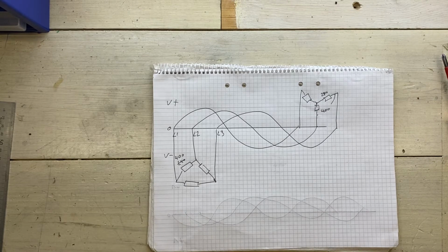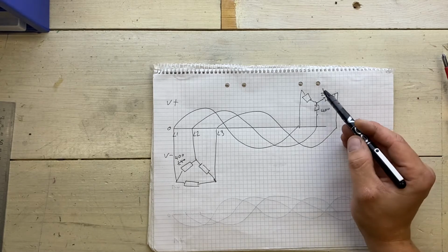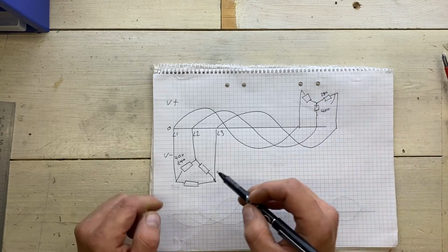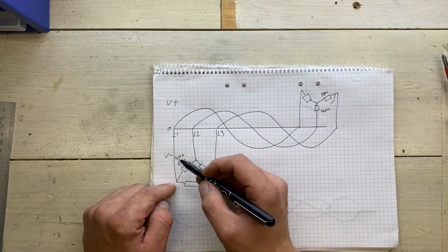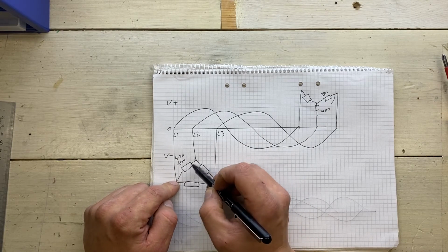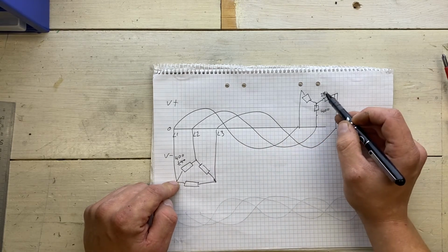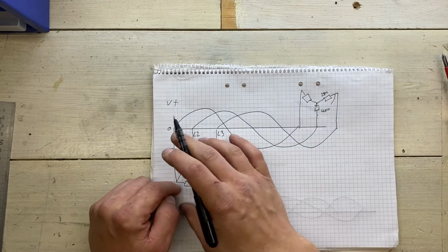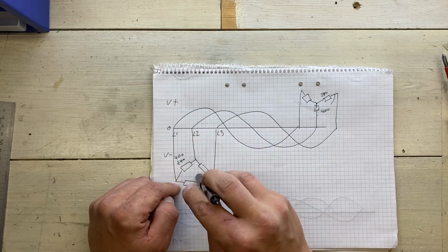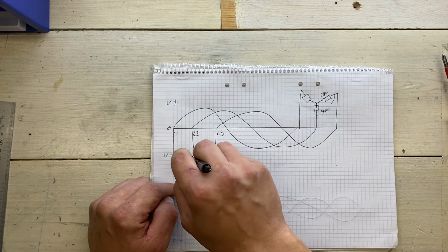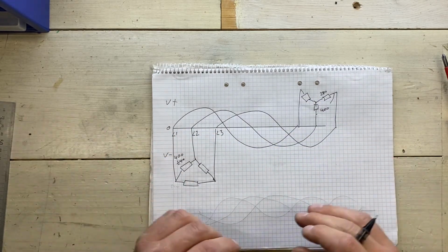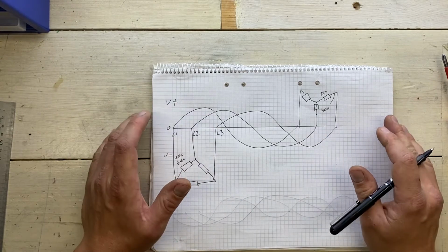But that also means that if you have 400 volt 3-phase, you need to connect it in the star configuration, because if you connected it in the delta configuration, you would actually have 400 volts across a coil only meant for 240, and that would fry it. Now if you have a motor that's classified for 400 and 690, then you'll use the delta configuration for 400 and the star configuration for 690, but these systems aren't that common and only seen within heavy industry.